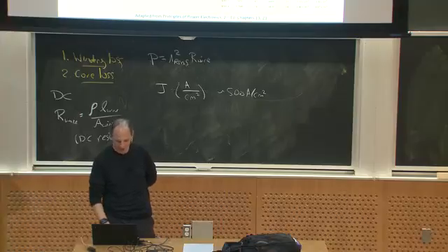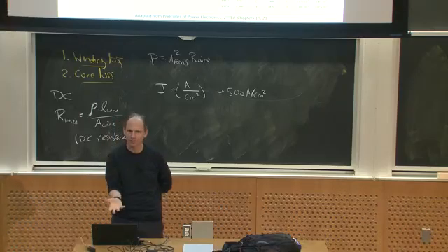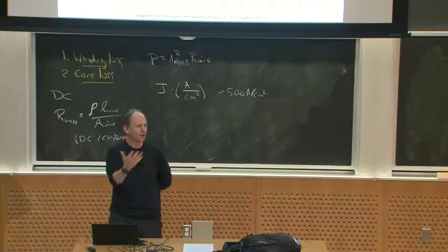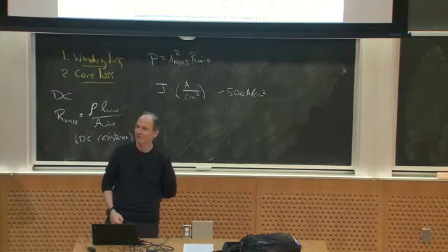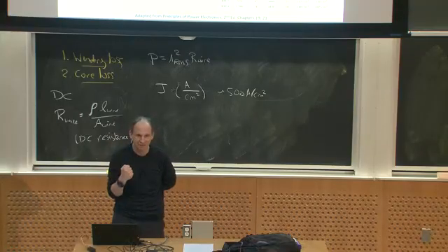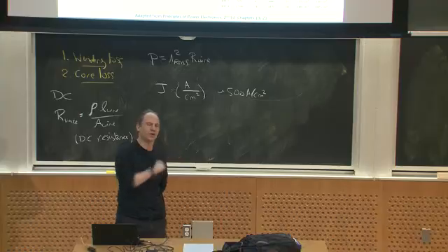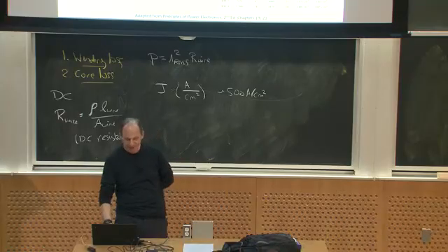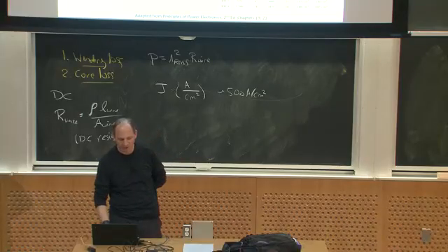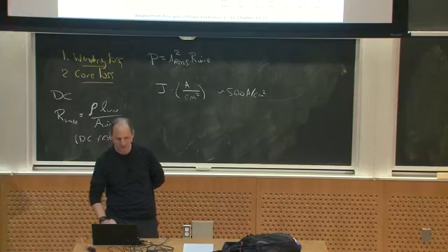And what we can see is maybe you have a few hundred watts per centimeter squared for a big element and maybe much higher for a small element. And this is for a 25 degree C rise. On the one hand, maybe you can take more than a 25 degree C rise. It's not unusual to have 50. On the other hand, you also have other losses besides the winding loss. So maybe this is kind of representative of what might be allowable for current densities. And so you can see my number of 500 amps per centimeter squared right here.